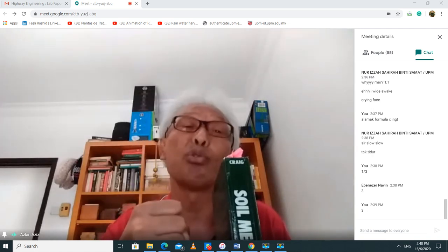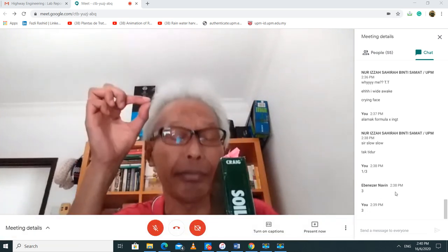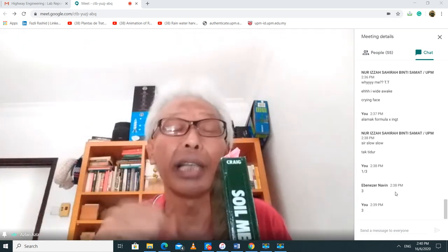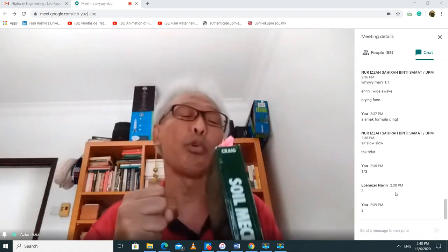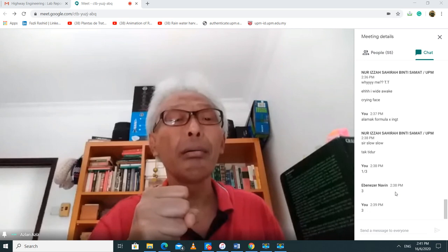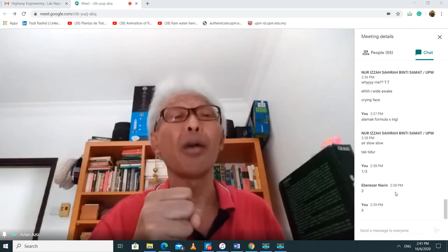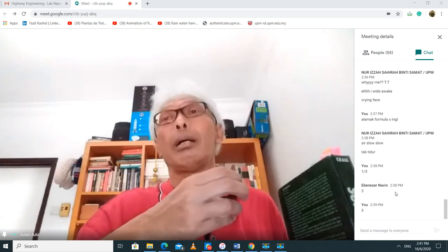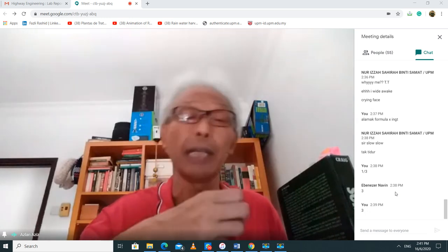Only that it fails through compression, and this is active. You see that Ka is only 1/3. It doesn't take much to compress an element of soil, and then it will fail. Now, if I move this retaining wall away from my element, the soil is also being made to fail, but now it fails through yielding. In other words, my element of soil is now increasing in volume. So that's why the Kp is 3.